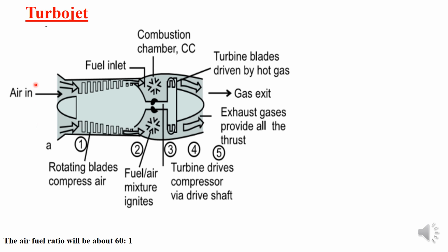After the diffuser, it is reaching the compressor. Whenever you talk about the open cycle of your Brayton cycle, most of the time we are using the open cycle in jet engines. The three components of your Brayton cycle are the compressor, the combustor, and the turbine. Before the turbine we have the combustor. So you have the compressor, then the combustor, then the turbine. Then the exhaust will be left to the surroundings.